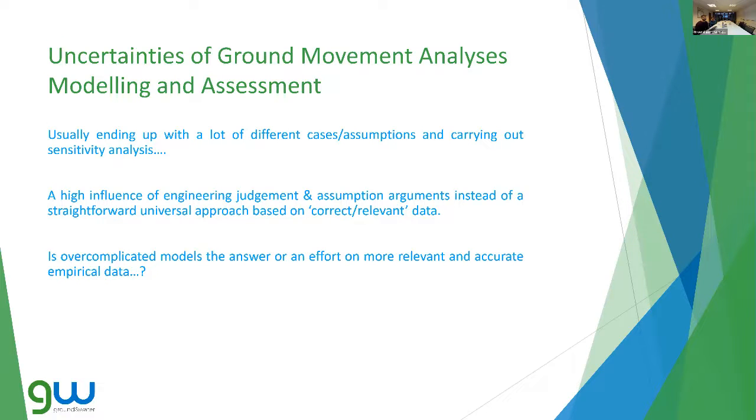And lastly, shall we use overcomplicated models such as finite element analyses? Obviously, these are very powerful models, but you need to have sufficient experience with them and knowledge of geotechnical and structural parameters in order to model and analyze effectively. These also take a lot of time and they're quite expensive methods, and that cost will obviously be passed on to the client. So could you use an elastic analyses method, which is a little bit more simple?